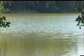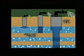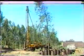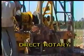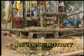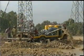As only 3% of fresh available water occurs as surface water, shallow and deep wells are made to tap groundwater. Introduction of well drilling machinery such as percussion, direct rotary, reverse rotary, etc., has made possible the recovery of groundwater in large quantities and from depths up to several hundred meters.